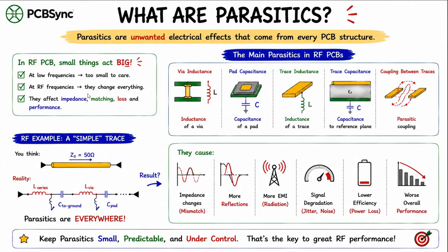If you look at RF design, today we're going to reveal five hidden issues. Sneaky via capacitance and skin effect, cutoff loss, and roughness of copper traces. Normally, you can hardly see them, but they secretly eat away at your performance. What's frustrating is that the PCB won't give you any error messages. In any case, you probably won't get any warnings until you start testing and the VNA begins to teach you a lesson.